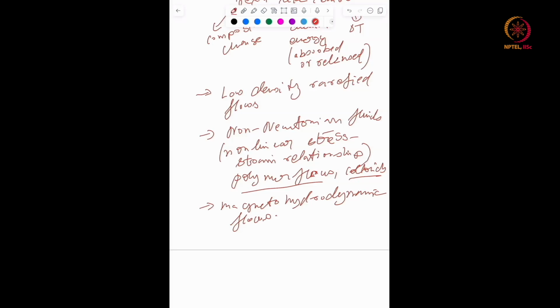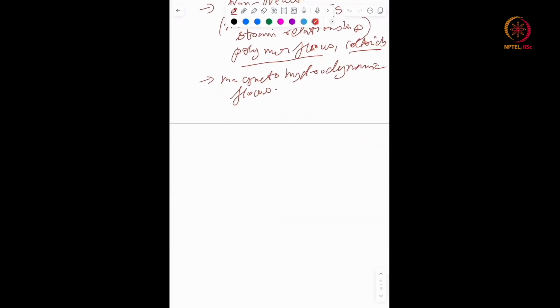Okay. So similarly, when you do fluid mechanics, you depend on something called similarity and non-dimensionalization, because when you non-dimensionalize things, you can use the results across experiments, across systems. You need to identify the parameters which describe the system in a non-dimensional space, so there are no dimensions attached.